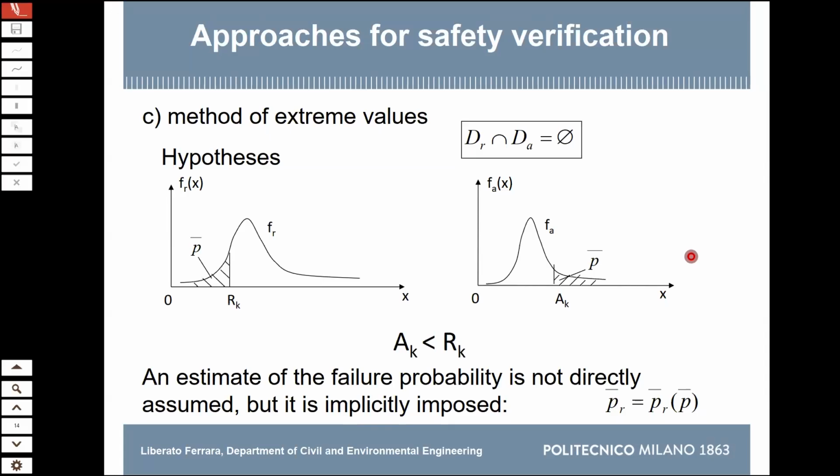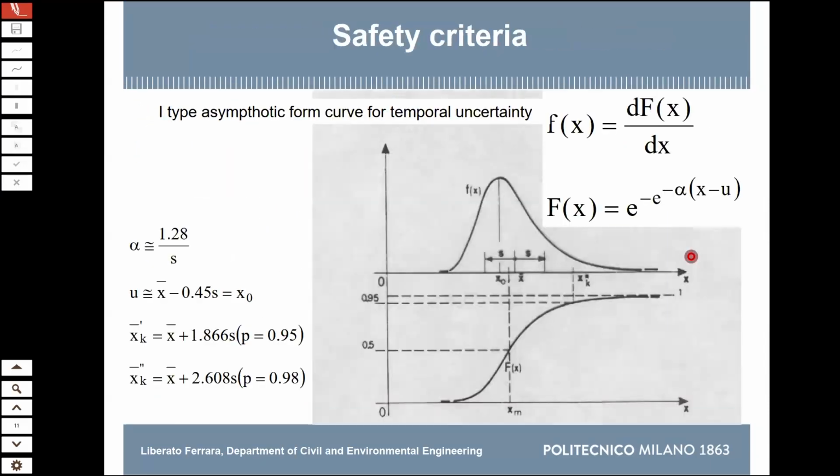Log normal, yeah. Compressive strength is log normal. Well, as I said, this is a distribution where the logarithm of your strength is normally distributed. So you have to go through a double mathematical passage, but then in the end it's very easy.